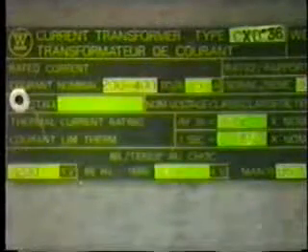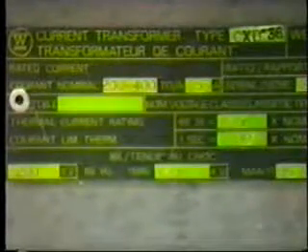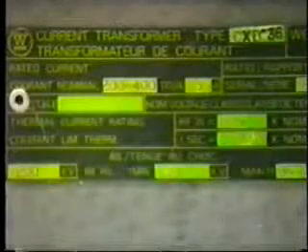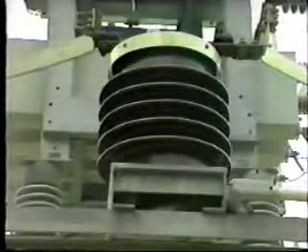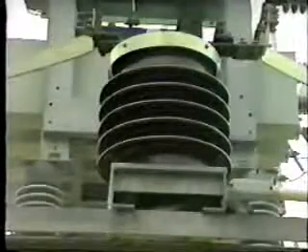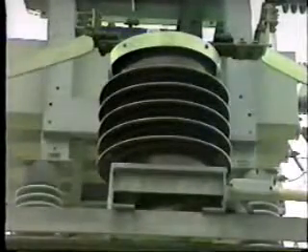As there are no phase shift problems across a bus, the 3-phase CTs are normally connected in Y. In order to improve accuracy, it is important that the burden on CTs be kept as low as possible. Therefore, the CTs should not be used for any other purpose. For the same reason, the leads connecting the CTs should be of ample current carrying capacity.